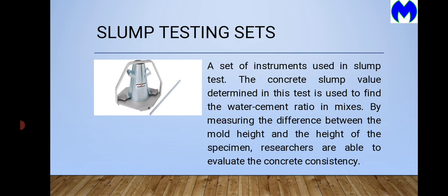The concrete SLUMP value determined in this test is used to find the water-cement ratio in mixes. By measuring the difference between the mold height and the height of the specimen, the researchers are able to evaluate concrete consistency. Okay, ano ba yung SLUMP test?